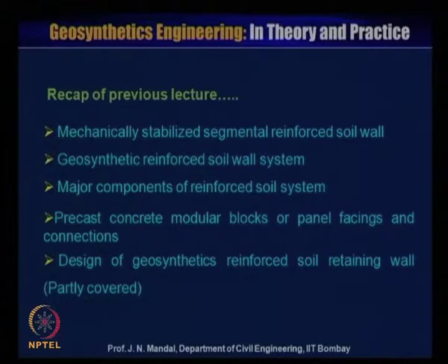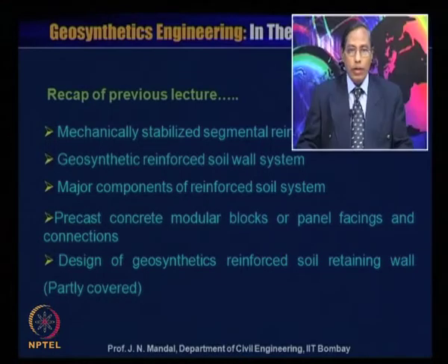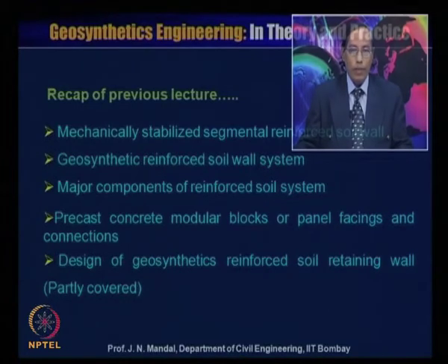I will now show the recap of the previous lecture. We covered mechanically stabilized segmental reinforced soil wall, geosynthetics reinforced soil wall system, major components of reinforced soil system, precast concrete modular block or panel facing and connection, and the design of geosynthetics reinforced soil retaining wall, which was partly covered.